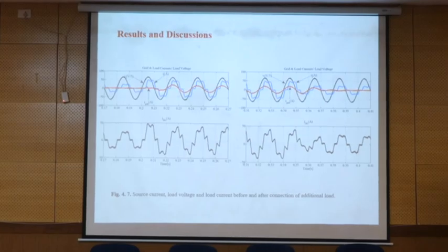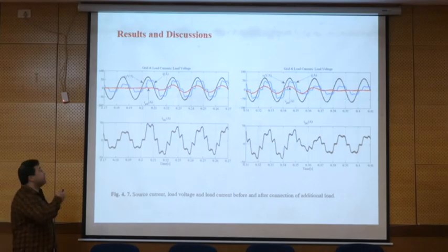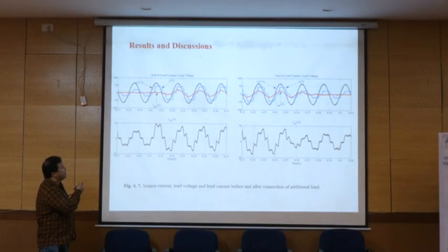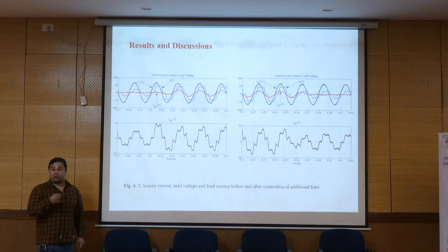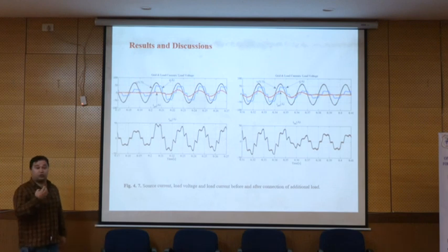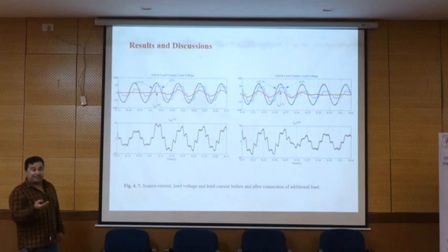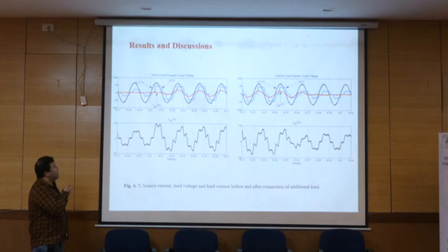After some time, you see that it's a steady state. Okay? So it's because of this filter and PI controller. PI controller is not too fast. Forget that filter, and if you don't tune your Ki and Kp, later you see that this will be longer and then it's not good. So as much as your PI controller reacts faster, this transient time will be shorter.